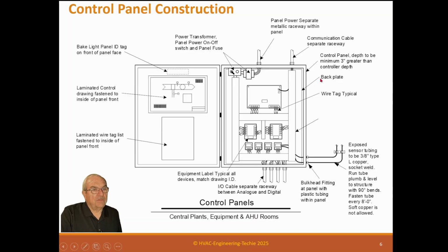So now this is some devices inside the panel. Here are some major devices. We have the controller, which is the master controller, and these are the I/O devices. These may be transducers or power supplies, whatever these might be. These may be relays down here or whatever. You put them inside the panel, and you run wire gutters around this panel so that when the control cables come in, they come into the wire gutters and run around, and they go to the device. It keeps the panel clean and neat and lets you see what's happening.